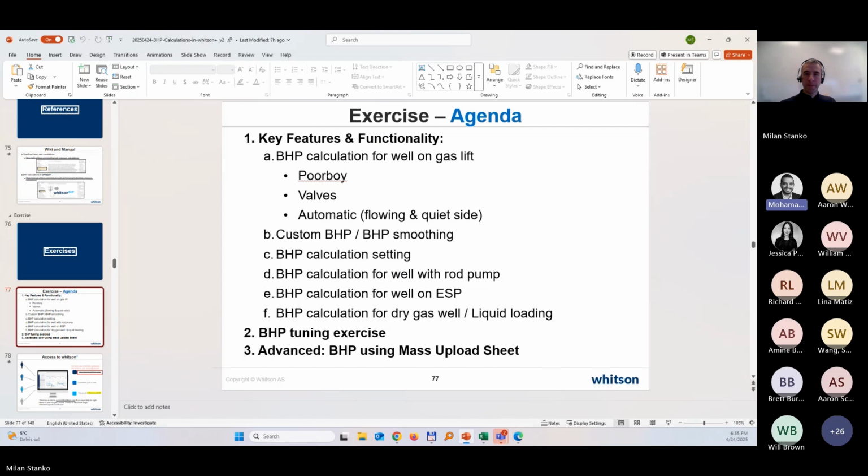I think there was a question from Michael on your thoughts on using, if you had rod pump and plunger lift, what are the issues with calculating the bottomhole pressure just through the tubing, making some assumptions on the average rates that are actually flowing through the tubing, instead of doing it through the casing side.